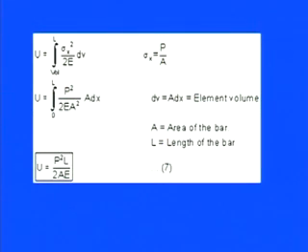So these are the main parameters through which we can calculate the strain energy of any element. We need to calculate the area, check what the material is and the corresponding Young's modulus of elasticity, and know the length and the load. According to the varying load, we have different elastic energy, or strain energy, in elastic form.